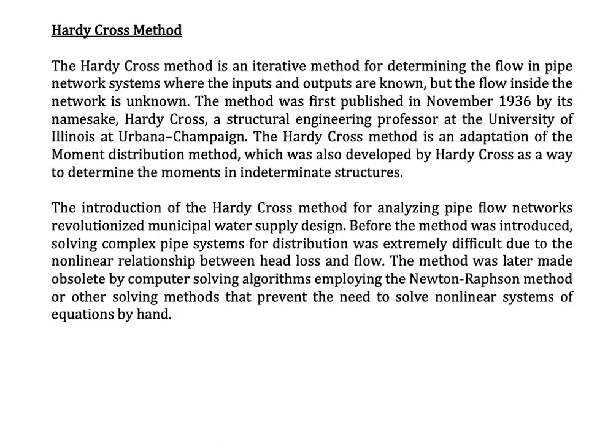The Hardy-Cross method is an adaptation of the moment distribution method, which was also developed by Hardy Cross as a way to determine the moment in indeterminate structures. The introduction of the Hardy-Cross method for analyzing pipe flow networks revolutionized municipal water supply design.